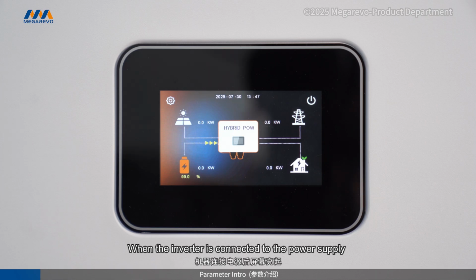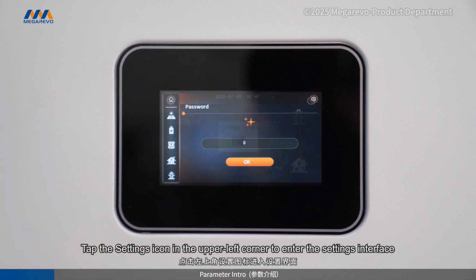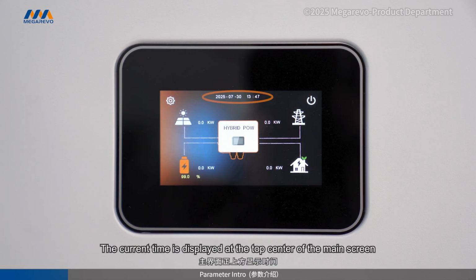When the inverter is connected to the power supply, the screen lights up. Tap the screen to wake it from sleep mode. Tap the settings icon in the upper left corner to enter the settings interface. Tap the home icon in the upper left corner to return to the main interface. The current time is displayed at the top center of the main screen.